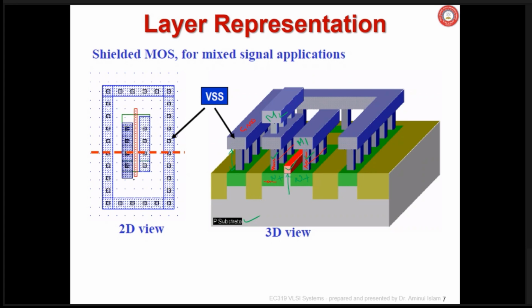By an etching process, different etching processes are there, you can remove the silicon dioxide and make a hole up to this depth, and then that hole is filled with tungsten at the bottom. This is the bottom layer, just above the silicon substrate. The tungsten can withstand high temperature processing. Upper metal vias are filled with aluminum mostly, but the bottom one is with tungsten.